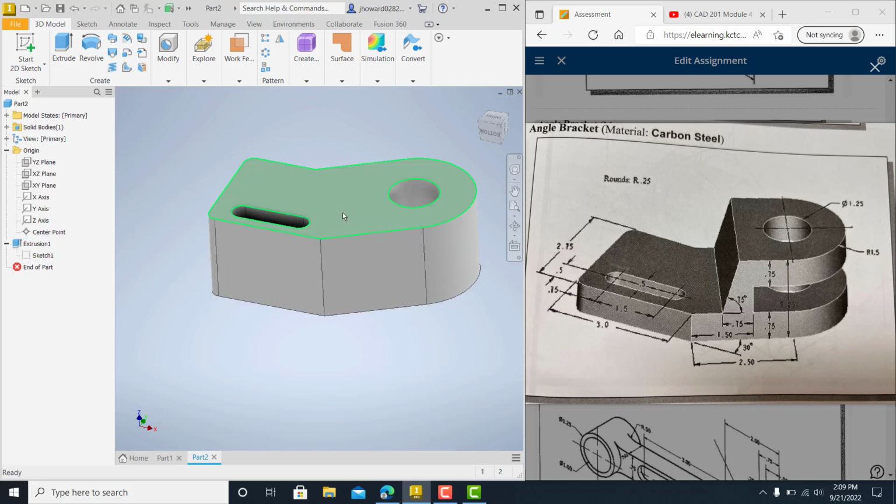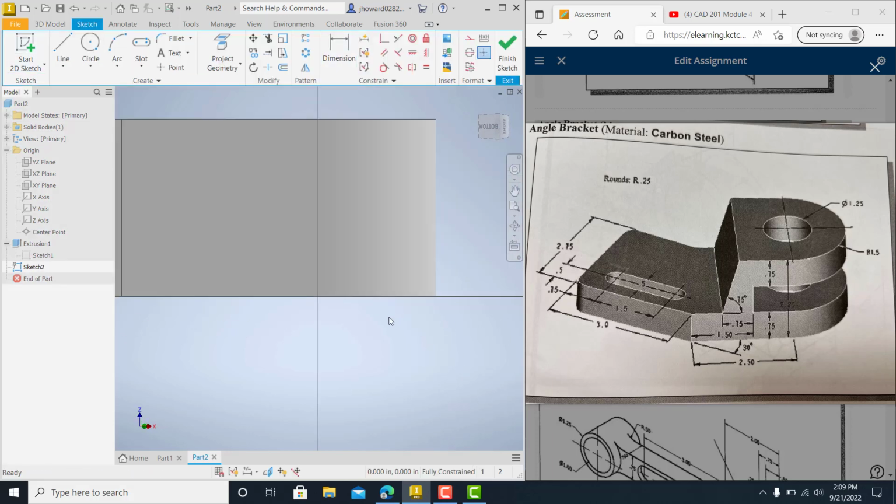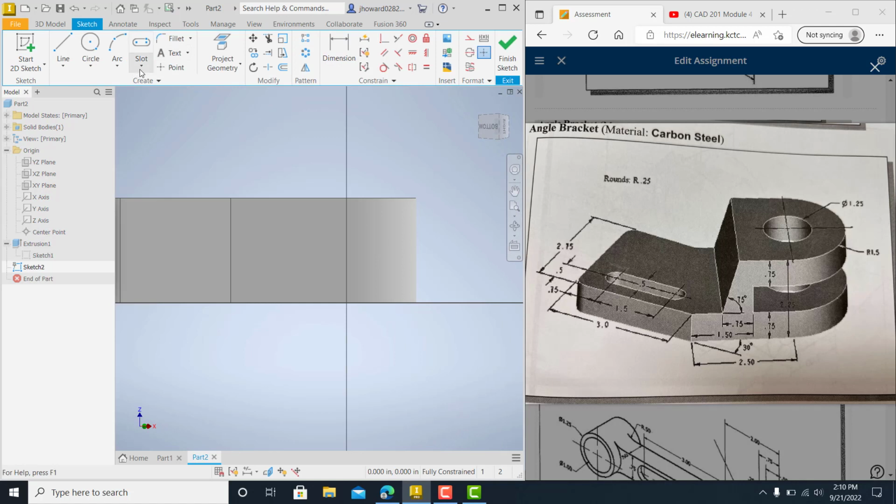Now the thing we got to do is we got to cut this out right here. So this right here is where I need to be to start a new sketch. Click that right there. We're good. So I'm just going to put me a rectangle in now. And I just roughly put it in there. It doesn't matter. We'll put the dimensions on it afterwards. Thickness 2.25. Overall it's 0.75 on the bottom. So that will locate it. Locates that in the middle.